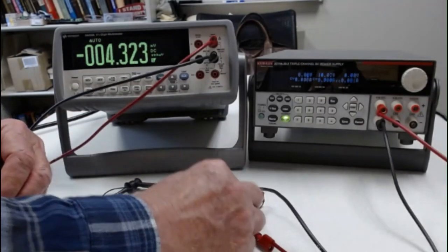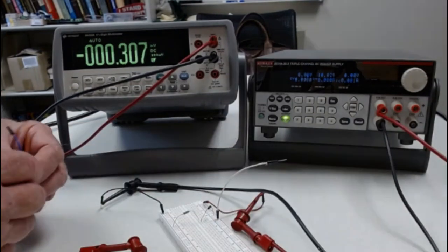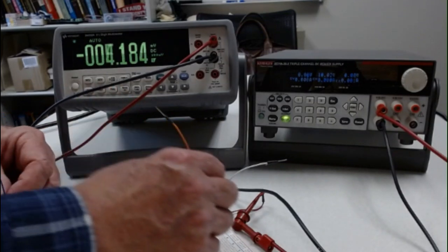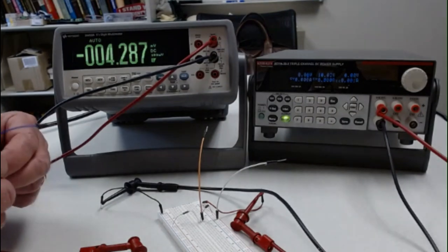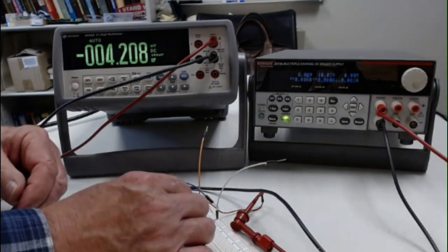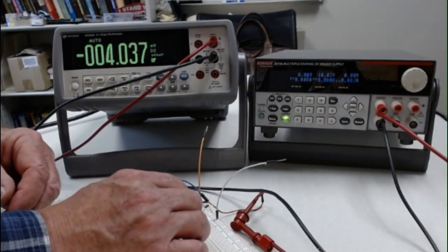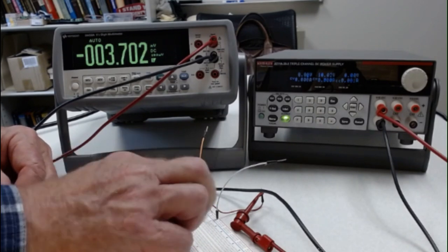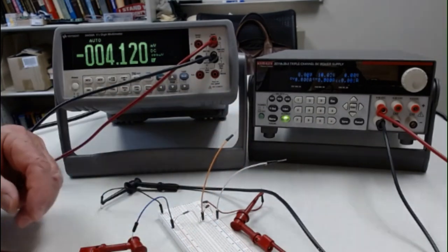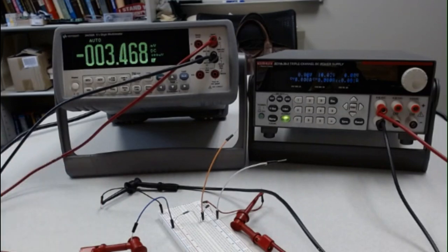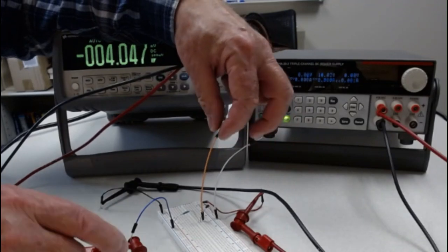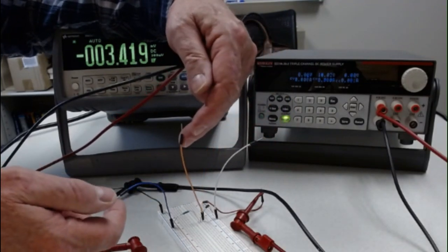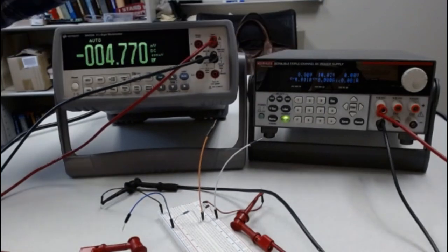So I'm going to put a jumper at each of these 3 points so that when we do these voltage readings, we're not touching the actual devices. We're just touching these extra points. So we're going to try to set this up so that it's a little easier to do this reading. So this would be the voltage across the diode, and this would be the voltage across the resistor.